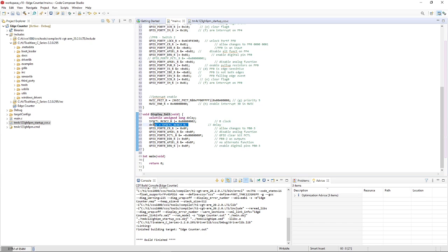Then we'll set this delay here equal to, actually, I don't even want to do that. We're actually just going to do the same initialization with falling edges. And again, the only reason that these are here is to give the clock on those ports time to catch up. That's all we're doing with these. Some people actually just use a throwaway value, but if I have other assignments I can make, I just make them instead.